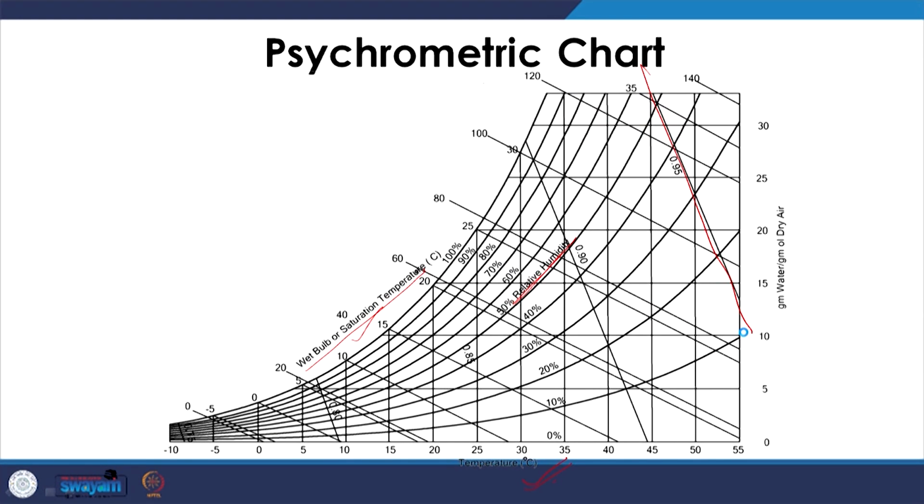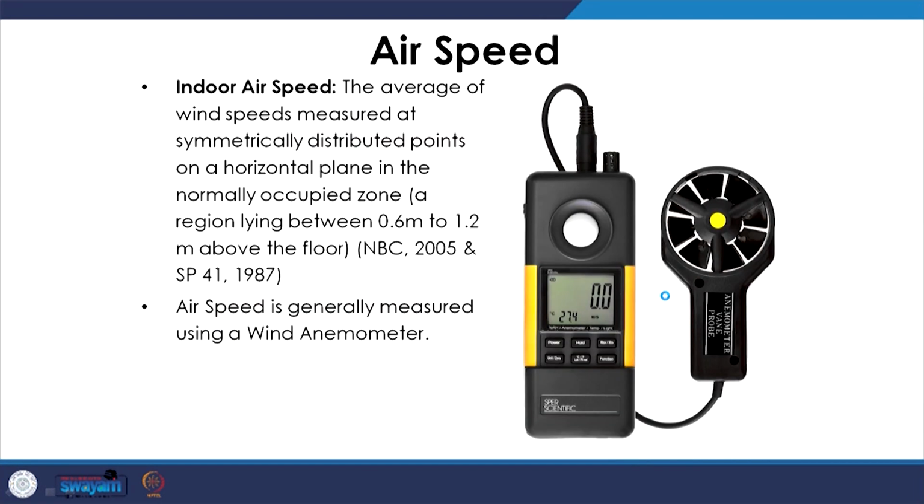Now, if we look at the psychrometric chart again, very clearly the comfort range can be defined, the thermal comfort range which is experienced by human beings. So, the psychrometric chart was a good way of demonstrating, experimenting and also defining thermal comfort, but not in a very comprehensive manner, as other parameters, for example the air velocity and the personal factors, could not be taken into account.